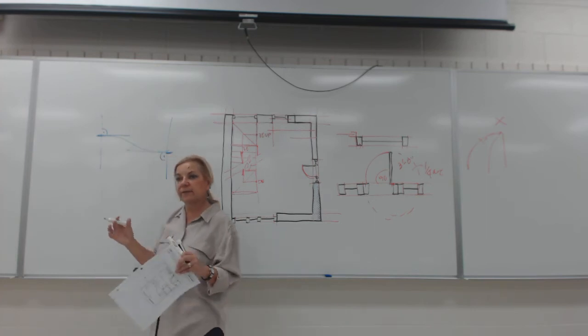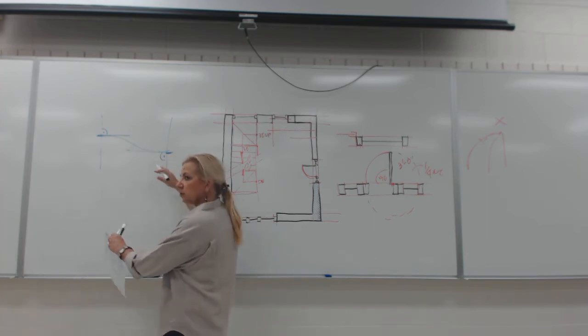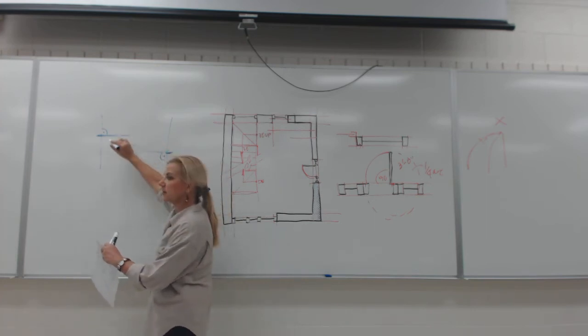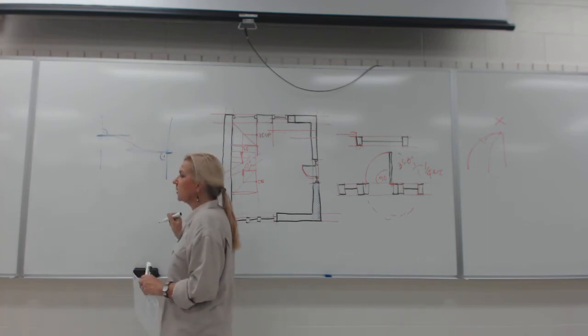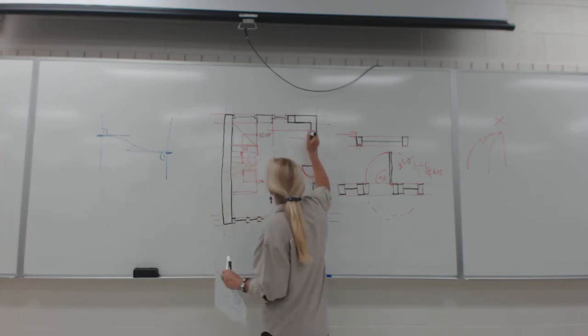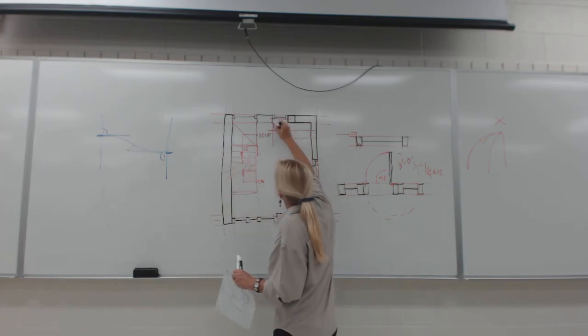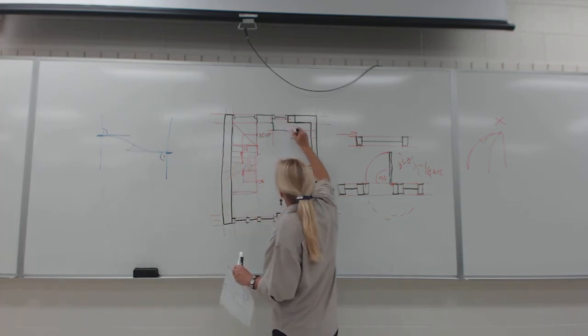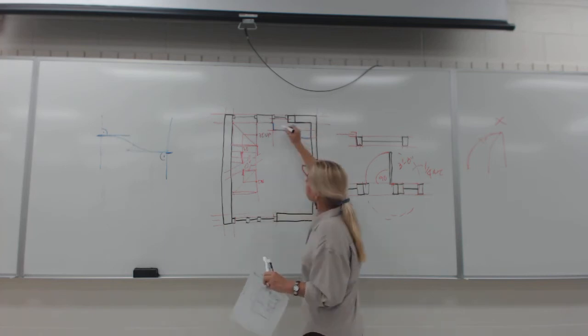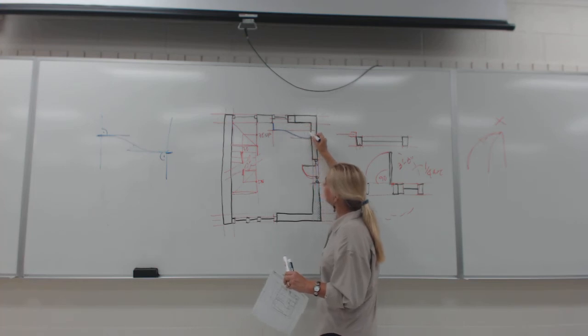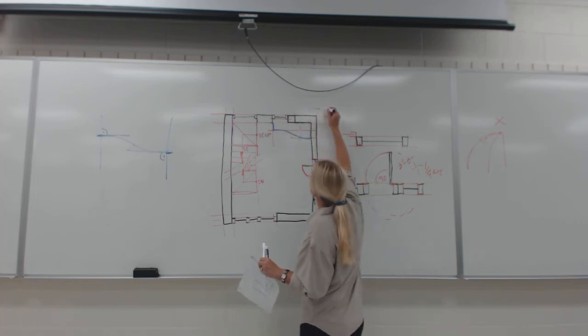So you would take the flex curve, place it right against the drawing where you picked some plus minus points, and you would create the curve and then draw it darker. So on the main floor, you would create these two walls. There is a straight line, and you would create a curve that represents that beautiful curve that was showing the opening to below. And we should really make a note that this is open to below.